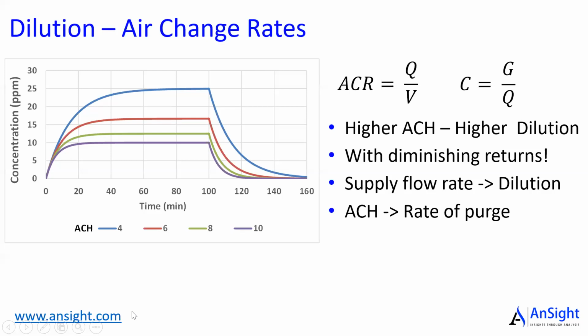So try to differentiate between the supply airflow rate and air change rate. The volume of the space specifically acts like an inertia or a flywheel effect. The larger the room, it will take longer time to purge and so forth.